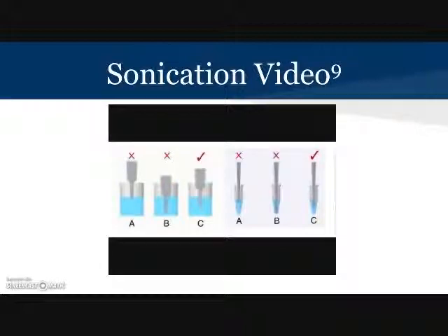Foaming often occurs with sample volumes below 1 milliliter. Foaming can also be caused when the amplitude setting is too high. Figure A will create foam, Figure B will not circulate, and Figure C indicates correct setup.